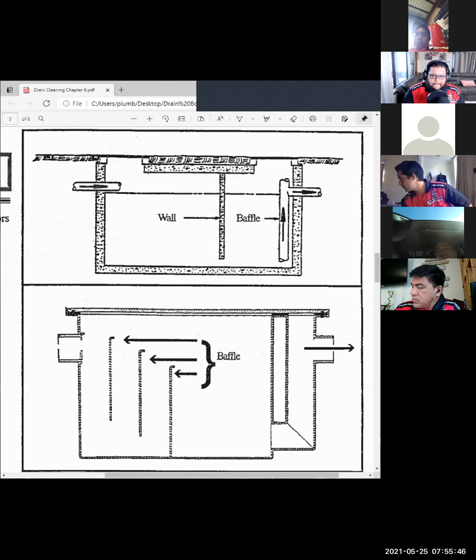On the lower interceptor, you've got these. Now, this is an interesting older style, and I don't see these very often anymore, but those are gates, and it's level 1, level 2, level 3. If those aren't in there, they won't hold. Guess what? The guy needs a new one. Now, the plastic ones they have now, and on Oahu, you guys have that one high-performing grease trap on the shelf, and it's like 500 gallons.